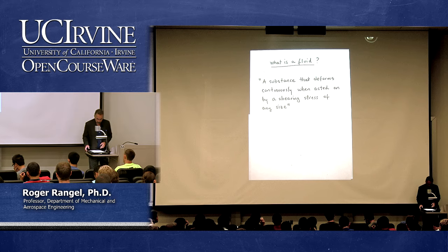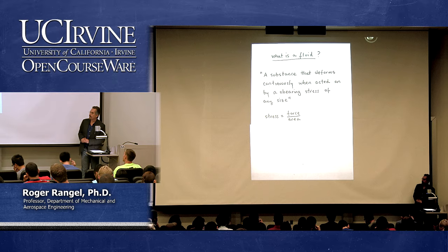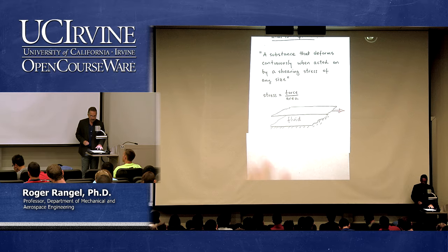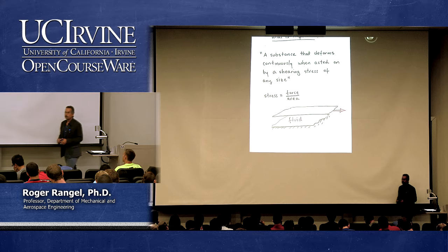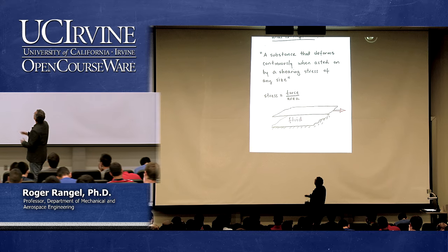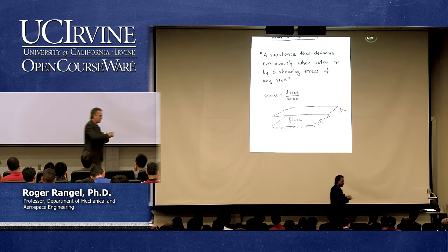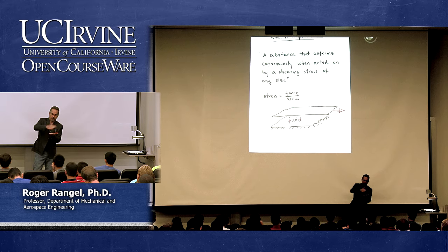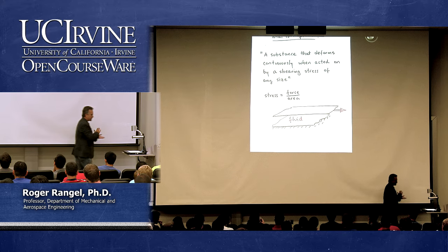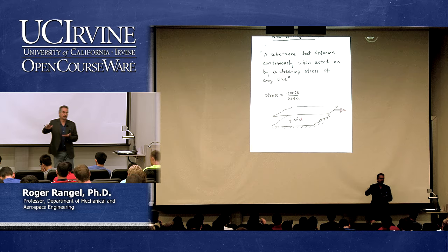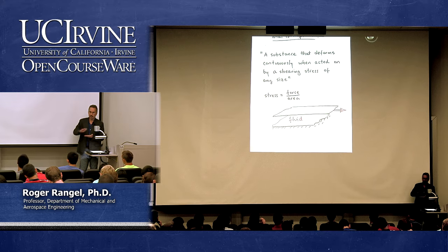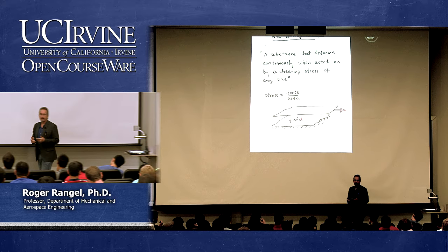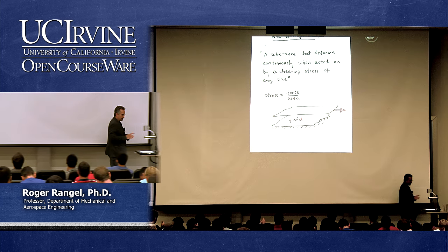All right, so here's a little picture of what's going on. So stress, force per unit area, you will never again forget that, right? So here is a simple experiment that I could think of. I could put a fluid, something that I think is a fluid, between two planes. So I build a little flat channel, two parallel plates. I keep one fixed, and I put the fluid in between the two planes, and I move the top one like you see there with the red arrow. It's moving to the right because I want to shear that fluid. I want to apply a stress that is tangential to that plane where it's acting. So obviously, if I do that, then this fluid that is in this gap will move in some form that we're going to determine as we learn fluid mechanics. But that would be a way.